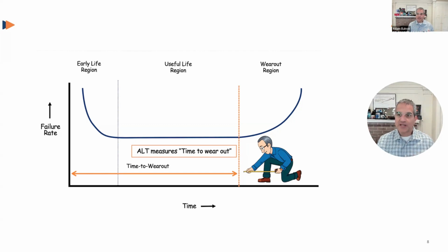So you would have to set that goal, as I said, as you're setting the design parameters, and then look at all the different types of wear out failure modes that can occur, the stresses related to them, and see if the design can satisfy that objective, and then make modifications. So you get to decide when the end of useful life is, and then modify the design to satisfy it. That is generally how the process goes.